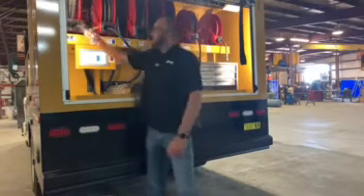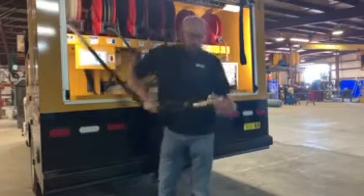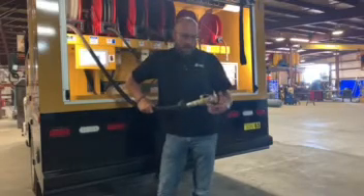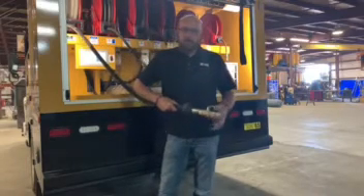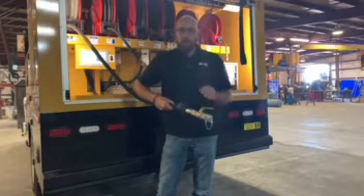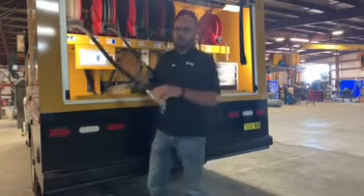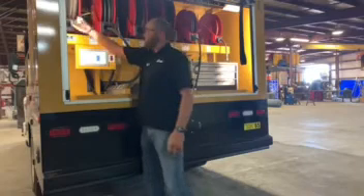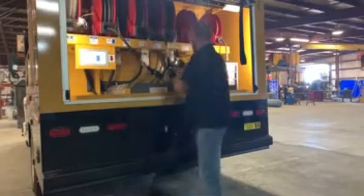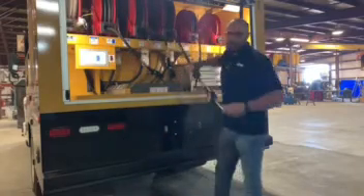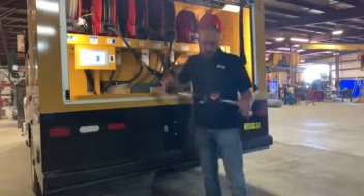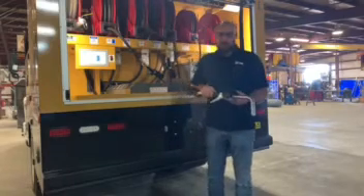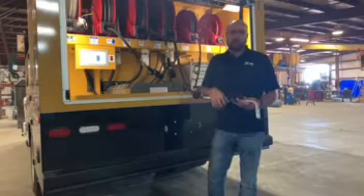To do your oil change, grab your used oil hose, disconnect this cap, plug it into whatever you're going to be using to suck the oil out with, turn the ball valve, and you'll suck the oil straight into your used oil tank. To be able to dispense new product, grab your meter, which is correlated with your respective fluid. Take this over there, pull the trigger, and dispense your fluid into the engine.